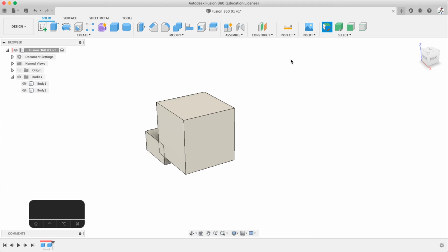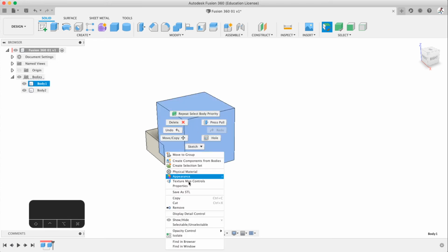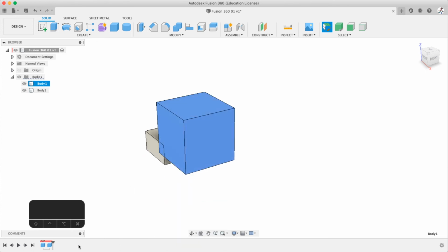The last few things we're going to talk about here is the history menu down here. This is the history timeline. This is sort of a new thing for Fusion. If you've been on a hiatus on the program for a few years and coming back to it, this is brand new. It's a wonderful thing. It does change certain workflow things. It changes this: remove versus delete. If you have the history turned on, which is the default function for Fusion,